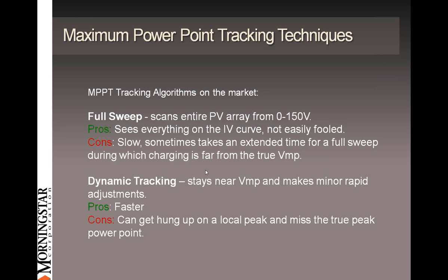So to do a better job than this full sweep, you can do dynamic tracking. What that does is the controller will slowly trace the IV curve up, get to the power point, and then it's going to stay there. And instead of trying to do a resweep, it's just going to look up, look down, and see if the power went up. If it did, it's going to shift maybe half a volt up or down the IV curve. And it's going to basically repeat this process quickly and inch up and down the IV curve, staying on the most efficient point. That works well as well, and you don't have those long sweeps.